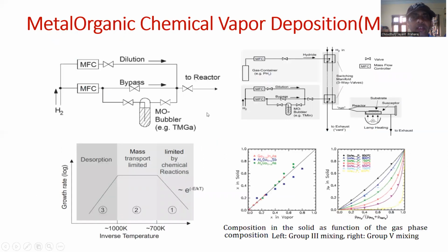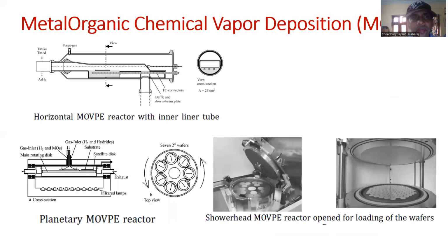Here we mention some epitaxial layer growth mechanisms. For example, there is metal organic chemical vapor deposition growth. There are the sources of metal organic compounds, and then there are the dopant sources that go and deposit epitaxially on the substrate, and then we form the device layers. Growth conditions need to be optimized in order to reduce dislocation densities, etc., and to get maximum photocurrents and photovoltages out of these devices. So these are some more details about the metal organic chemical vapor deposition layers.